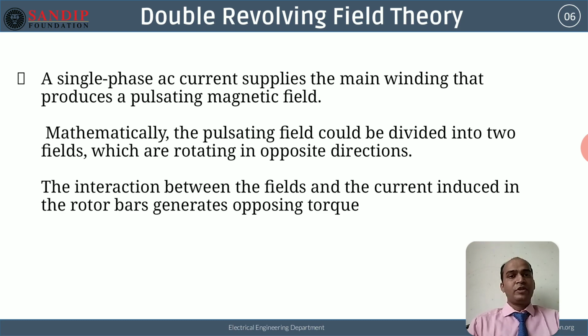First, the two magnetic fluxes should be shifted by 90 degrees with respect to each other, if one flux is horizontal and the other flux is vertical. Also, the two magnetic fluxes should be time quadrature. If the fluxes are represented as phasors, then there should be a 90 degree phase shift between them. That means there are two fluxes, one horizontal and one vertical, and these two fluxes are 90 degrees to each other.